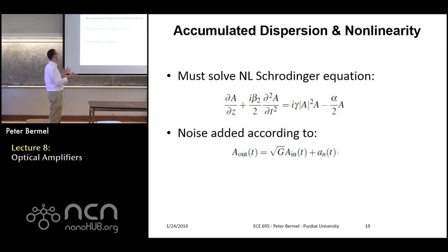So you can track how everything is affecting everything else, right? The reason this can be important is you could have a few things happening, like dispersion and self-phase modulation, and if they were just on their own, it wouldn't be too bad. But if they start interacting, they can amplify one another, and then you can have extremely high bit error rates.